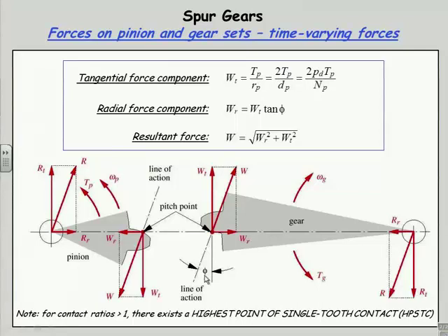And we have a pressure angle labeled phi, which we defined before in the previous lecture and also defined in kinematics, same idea for both gears and cams. And that defines the angle along, or the line, I should say, along which the true force lives. The so-called line of action is the term used in gears. We called it the axis of transmission in linkages. We called it the common normal in cams. It has a bunch of names that all mean the same thing.